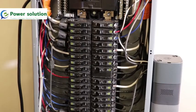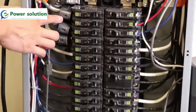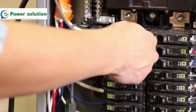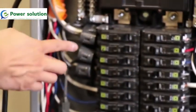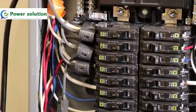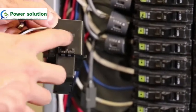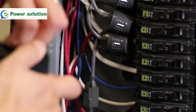Another thing to check during installation is that all of your load arrows are pointed in the right direction. So the circuit breaker feeds energy out to its load. You can see all of our CTs are marked so that the load is pointed in the same direction as the circuit. If you're using off-the-shelf CTs, you'll want to just double check that the load arrow is going with the circuit if you were to have used this system.